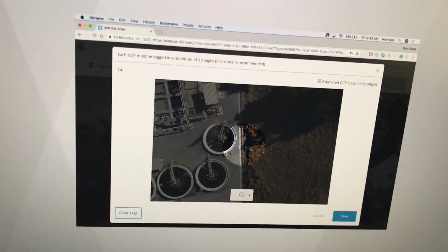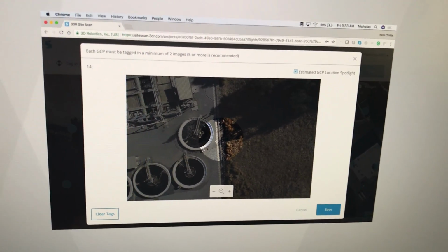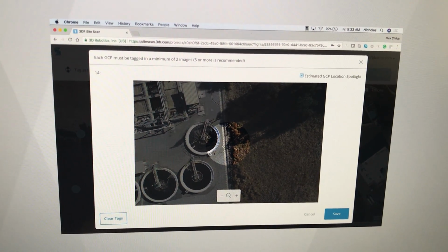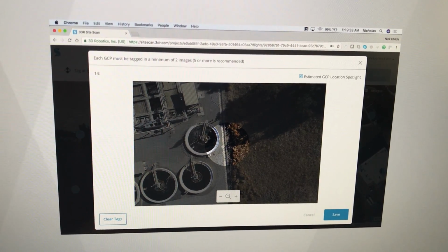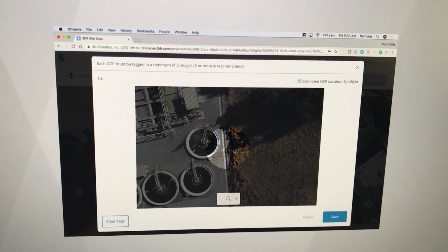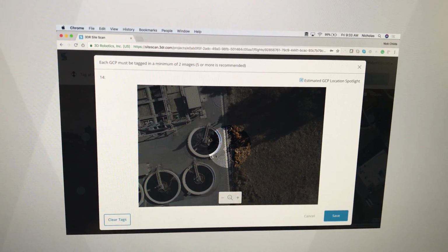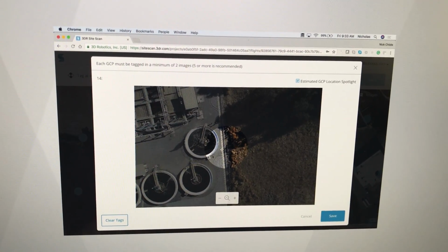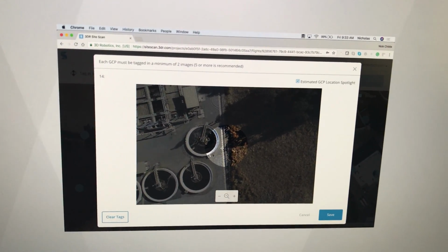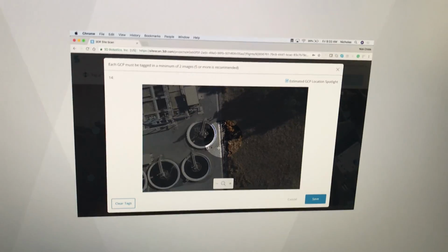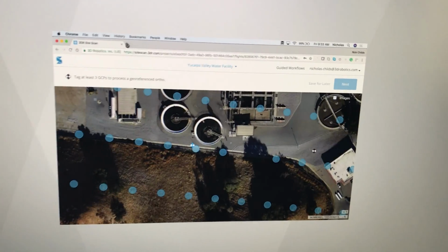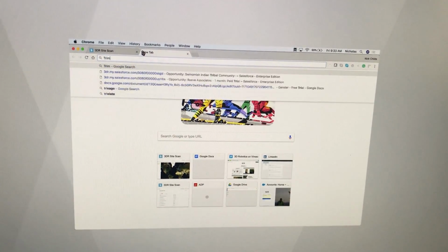Yeah, that's pretty crazy. It doesn't sound like it's going to be as accurate as a Trimble R7 or R8 unit. It depends on where you are. There's the Trimble network, so if you're closer to a base station, yeah. But if you're in a high accuracy zone, you're talking about the exact same as taking a total station and shooting a point. That I question. A total station uses laser sighting to get millimeter level accuracy, and I don't believe that you can put a puck on a phone and get that kind of accuracy.